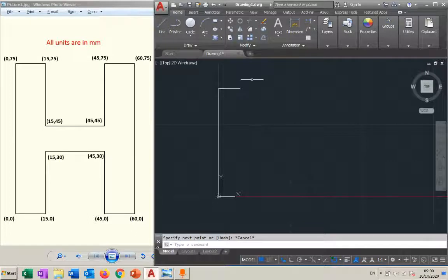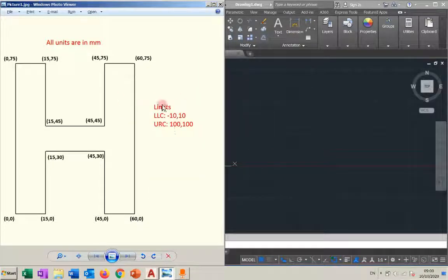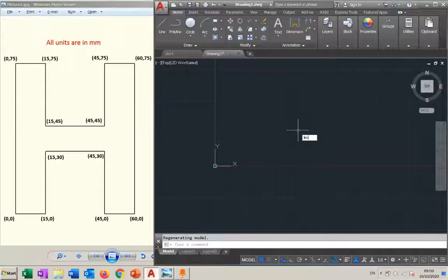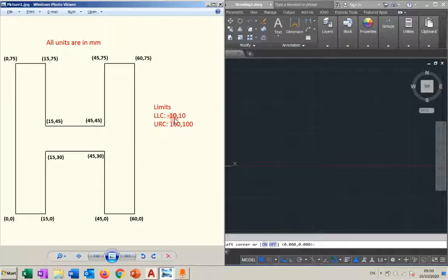But let's say that I'm just gonna delete those two. We're gonna use limit to see, let's say that we haven't started drawing, we set the units. I'm gonna start setting limits to see what is the difference between limit and the other methods in zooming. Now, I'm gonna start limits. Remember, limits is optional. You don't like it, don't do it. Now, I said I'm gonna give you the coordinate. It's supposed to be -10, sorry, here. It should be -10 here. -10, -10.